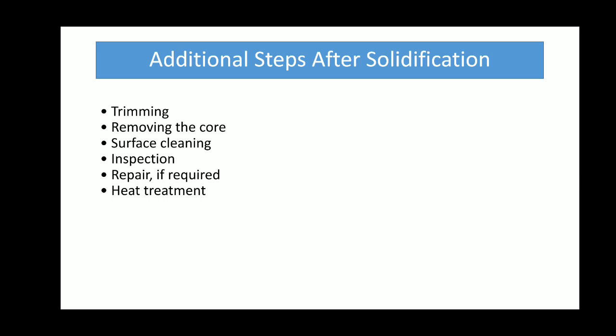Now, even though we know that the casting process most of the time can be a near net shape process, that means in a single step it's possible to impart whatever the final dimension is, as well as the different types of processing required. We can even give holes already in the cast, so we don't have to go for a secondary process. Similarly, it's possible to give certain surface textures, maybe threads, etc.